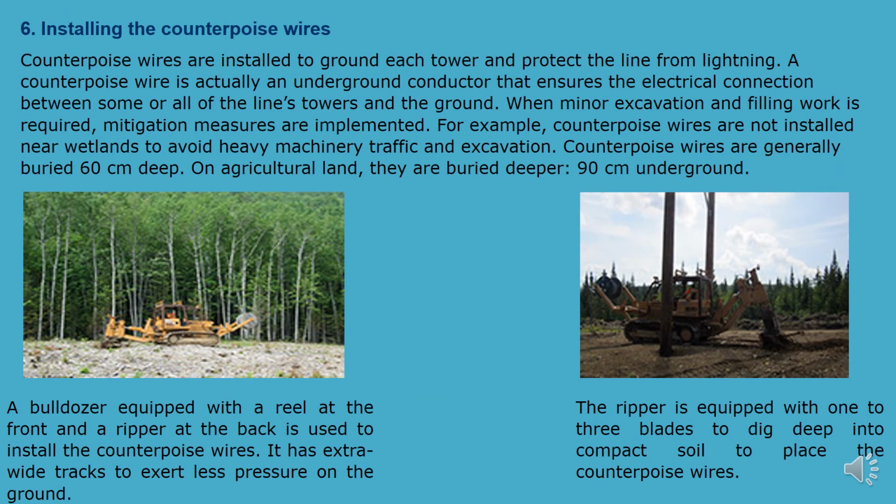Now the sixth step is installing the counterpoise wires, right? Once the tower is installed, then we have to use the cables or wires, then we have to use some counterpoise, right? So why do we have to use the counterpoise for each tower? Because of, if there is hard rock below the foundations or below the ground, right?